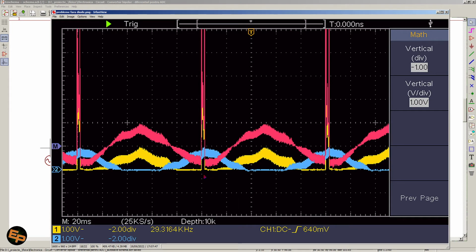It goes negative, you know, and because the input signal goes negative, the output of that particular op amp goes to the maximum voltage possible, and overall we get this annoying and not desired behavior. Okay, we must prevent at all costs the op amp from receiving negative voltages.